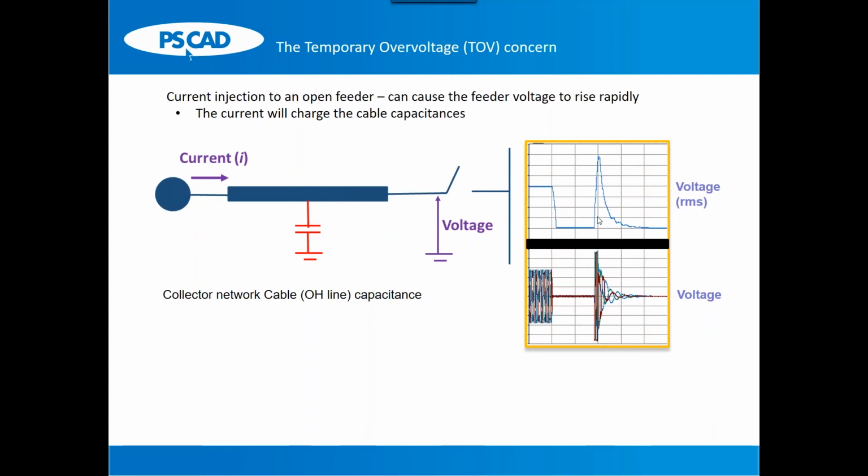You can see the RMS voltage as well as, of course, the instantaneous actual voltage shoots up for a few milliseconds. Okay, and in this particular case, the wind turbine controls have acted in an acceptable manner, and had just slowly ramped down the voltage to 0 because the feeder is open.